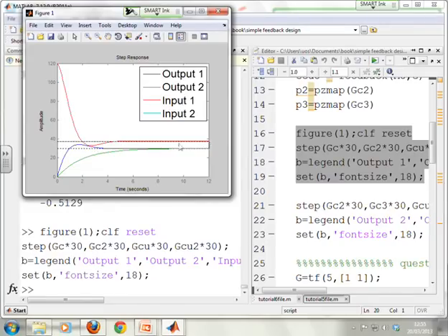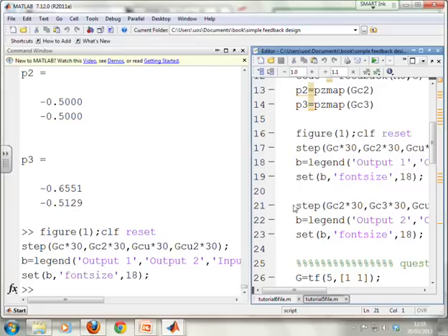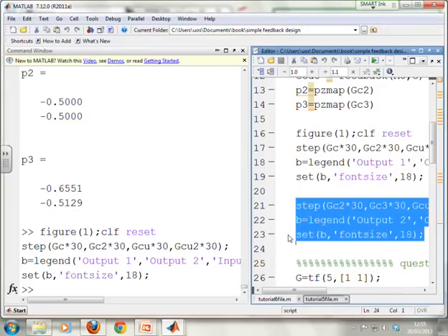If we look at the two outputs, with the original controller, very fast response, slight overshoot, it was underdamped, but settles quite quickly. With the heuristic, not nearly so fast, settles a bit more slowly. But of course, you've got the faster response by having an input here, which was unrealistic. Now, what about if we push the PI just a little bit harder, as we said, by going to the limit?